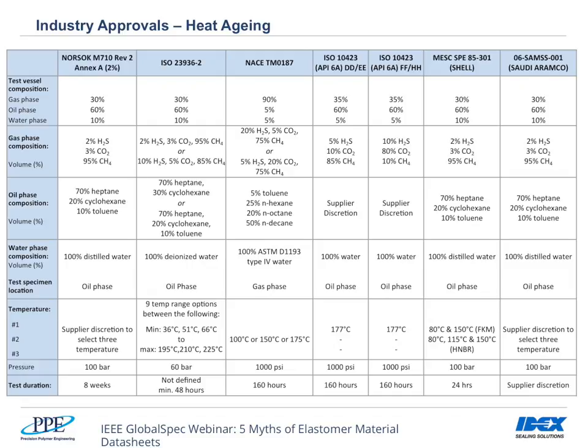But essentially, some materials perform with some hydrocarbons better than other hydrocarbons. For example, HNBR and nitriles are not good with toluene. If we remove toluene from the equation, it means it's not an influence. If toluene is not present in the application, that can be a good thing. In a similar vein, you can discredit a material unnecessarily by selecting inappropriate hydrocarbons for the testing.